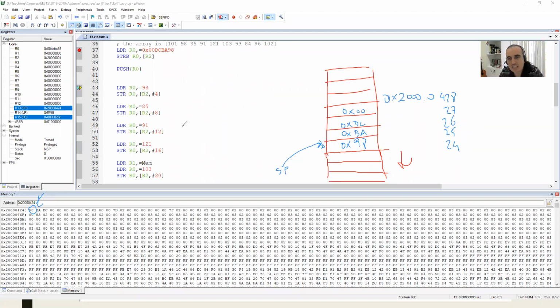So when you write something to the stack pointer, actually you can check it. If you have really written that value, you can check it. And stack pointer push always pushes 32-bit values. Any questions? I guess not. You can just write any value here to check the memory.